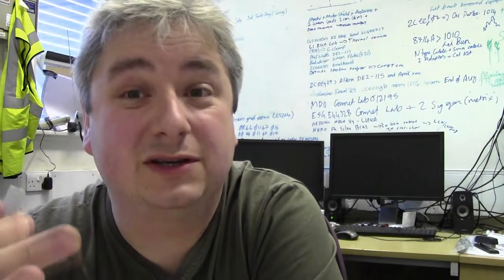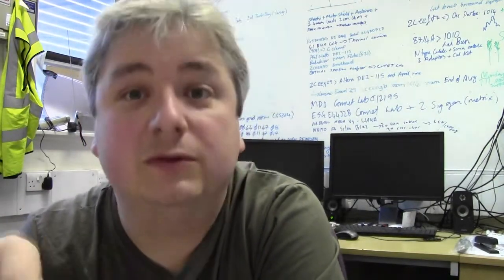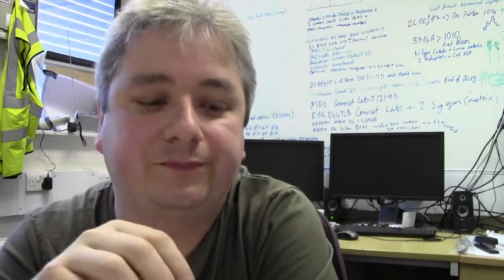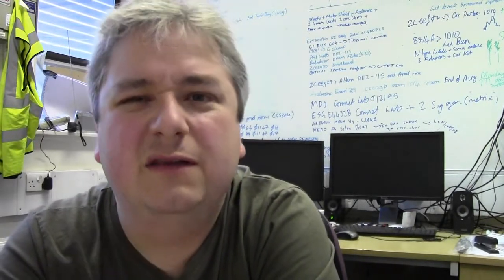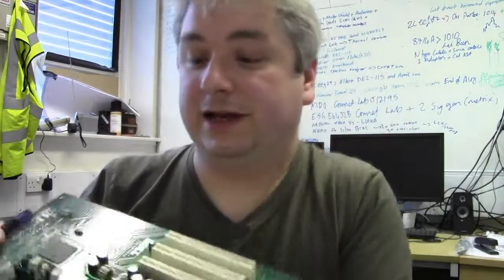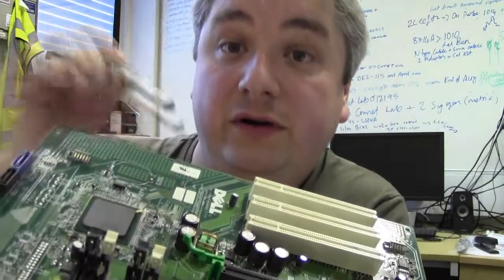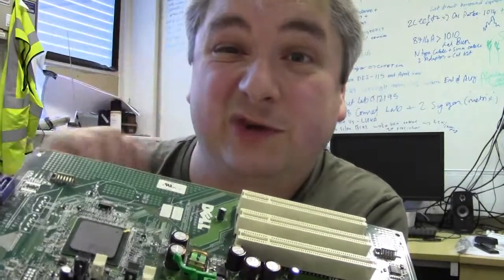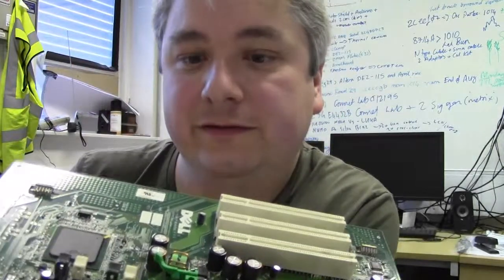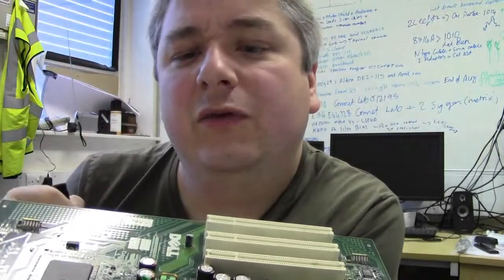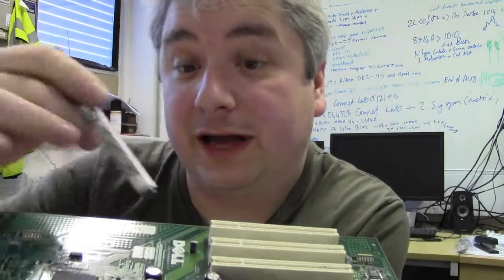If it's a blown component, one that's burnt out, you have to make some other observations. Take a look at the components that surround the actual area of your board. Find out what the most common one is, see if it matches up to the right footprint, and check for any markings on your board. If it's a cap that's gone, the top of your cap is probably blown off, leaving a little plastic ring at the bottom with two little legs sticking through it, so you get an idea of the diameter of your cap.